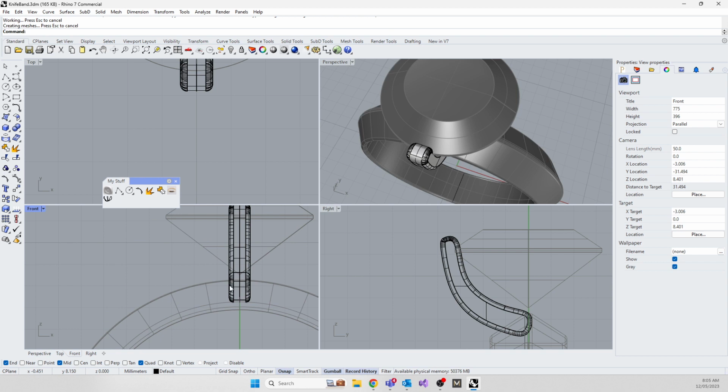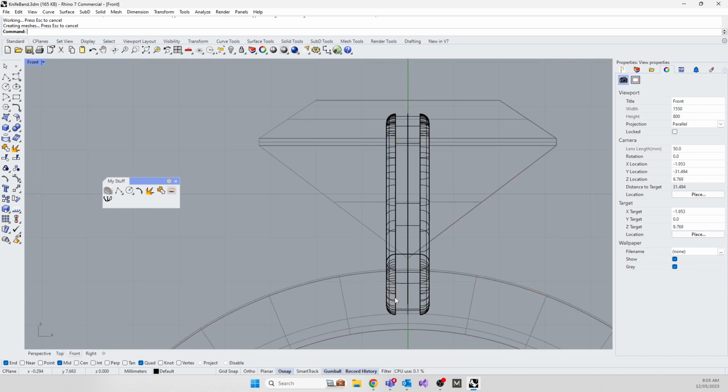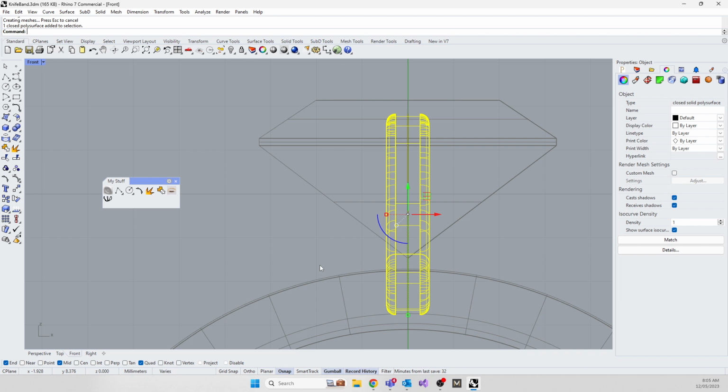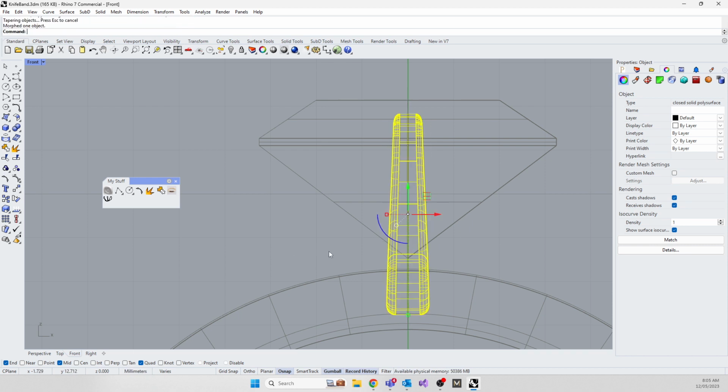Now in the real world, the bottom of a prong is always fatter than the top of a prong. What tool would we use? Normally it tapers towards the top. I gave you a tip over there what tool we're going to use. Yeah, taper. Remember, we want flat on, so we want to taper from there to somewhere above the prong. Not really important in this case. We want flat equals yes, because we only want to do it in here, and we want to taper it in something like that.